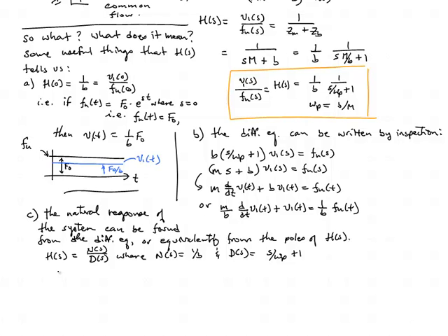What's the characteristic time domain form of its responses? And this will be true for a linear system, it will be true of all the responses, all the velocities, all the forces. If it's an electric circuit, it will be all the currents, all the voltages. Okay, we can find that simply by determining the poles of the system. In this case, there's only one pole. It happens to be at omega p.